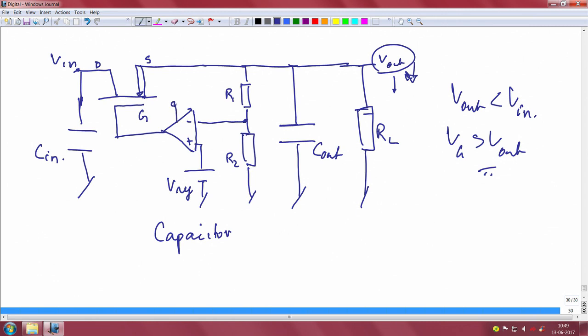How do you come out of this situation? Well, typically they use a charge pump or an external V bias, and then we will have to provide this higher voltage in order to ensure that this NMOS series pass element actually works.